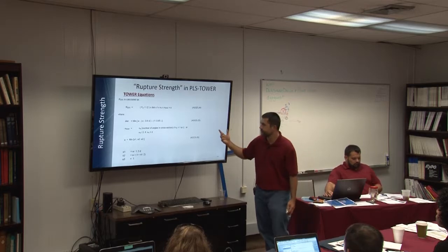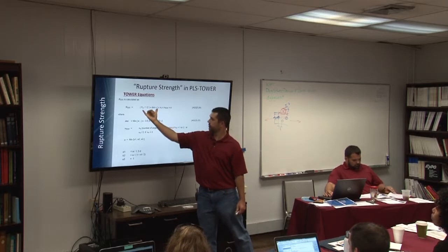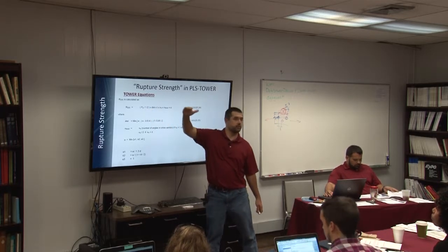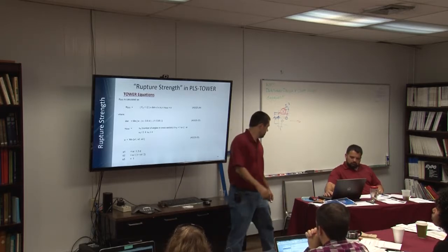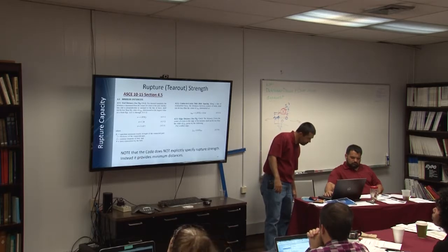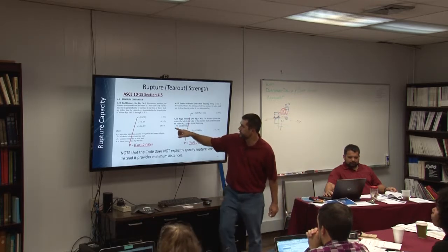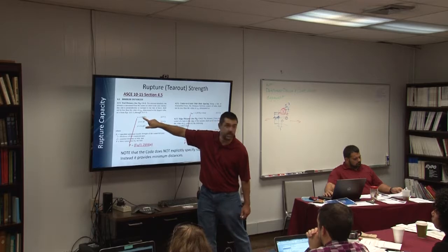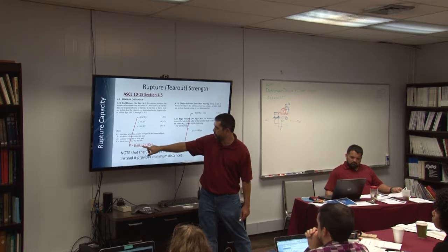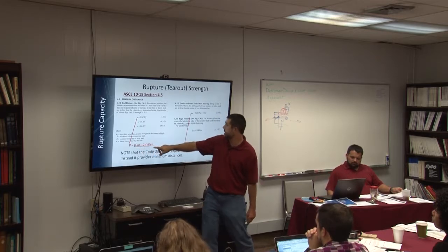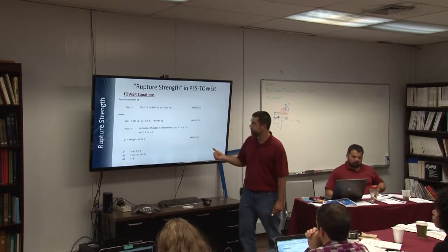So what do they have? What they do is this equation should look very familiar to that top equation for end distance. They've rearranged it so that the, actually, can you go back like 5? Oh, and go to the next slide. Yeah, here we go. So if they rearrange this equation for P, they get this, right? Where you have FU over 1.5 or 1.2 times the thickness times E. So you can go back one slide. Is that FU ultimate strength? Yeah, the ultimate strength of the material.